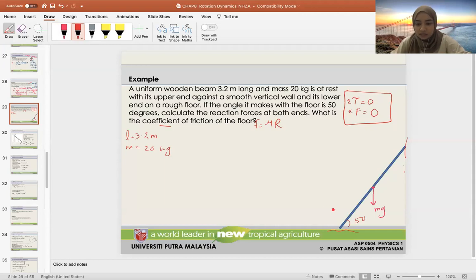If it's going to fall, it will fall this way, right? The motion to fall is this way, which means that our friction should be opposing the falling motion, but it's not falling because we have friction. If we don't have that friction, the motion to fall will go to the left. So to prevent the ladder from falling, the friction should be to the right, opposing it.